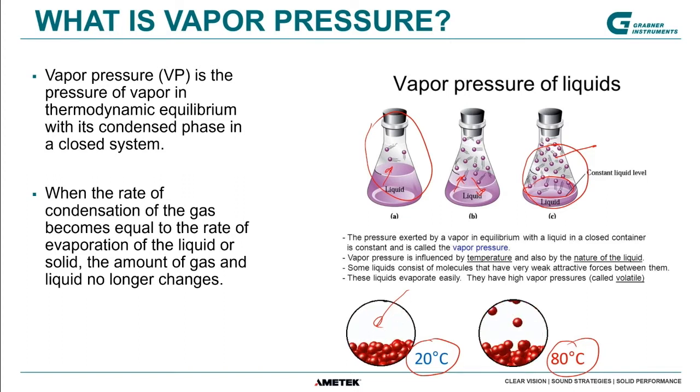That's important to understand, because that's why we have vapor pressure regulations which differ from summer to winter, especially if you have cold and hot seasons. In cold seasons, the standard vapor pressure of a gasoline can be adjusted much higher than during a hot season, because in the hot season you need to put less volatile components into your gasoline.